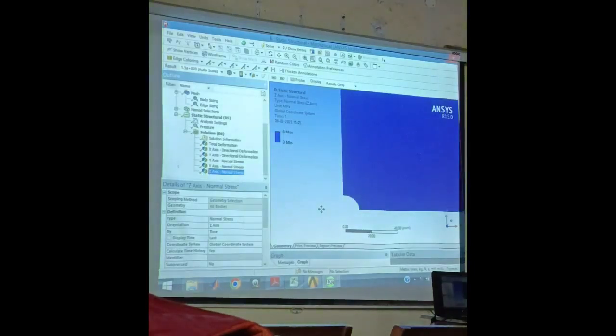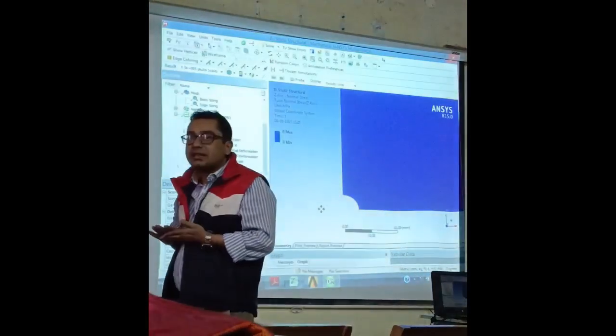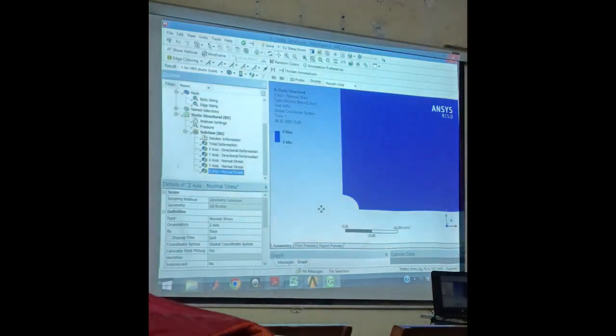Okay. Now what is sigma z? 0. Why is sigma z 0? Can you tell me why sigma z is 0? Because it is a 2D problem and there is no stress in the... No pressure. See, the problem may be 2D, but 2D does not mean the stress in z direction is 0. For a 2D problem, stress in z direction will be 0 when it is plane stress. Only when it is plane stress, that means we have assumed at the beginning it is plane stress.